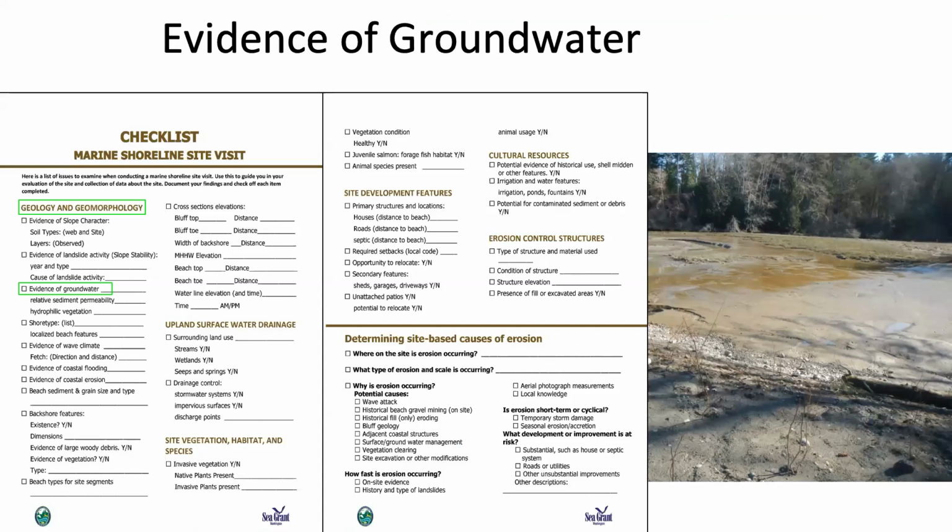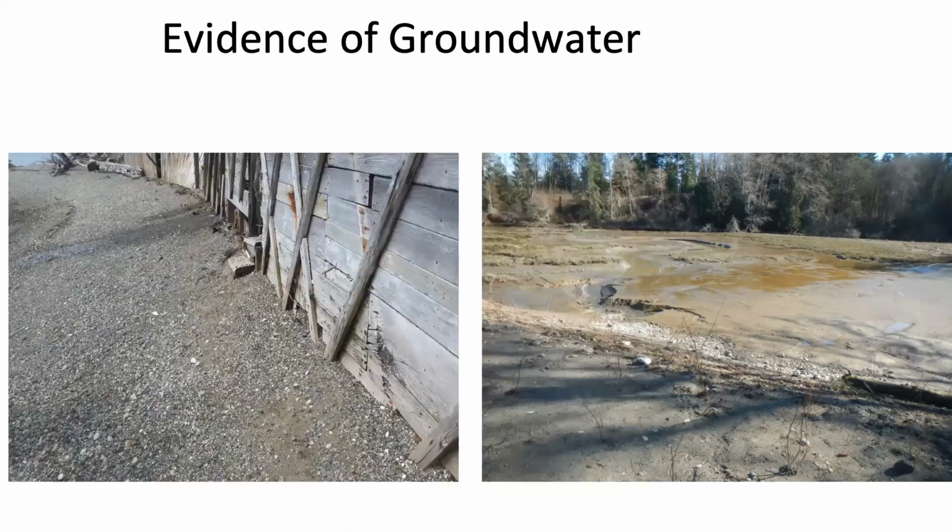So following the order of the checklist, let's chat about water. When it comes to slope stability, water is the bad guy, the bad actor. So consider what happens when you pour a bunch of water onto the ground. It turns soupy, and it can even turn into mud and flow like water. So groundwater suspends fines and can break down the cohesive bonds that strengthen soil above its angle of repose.